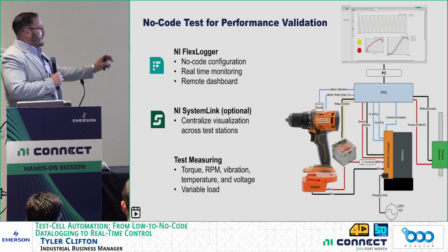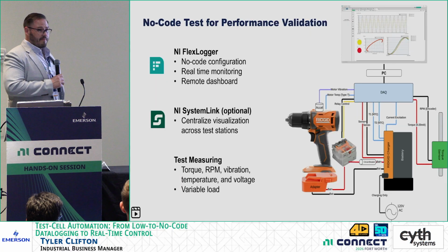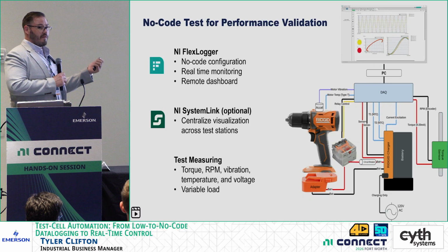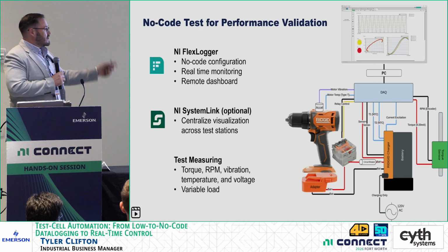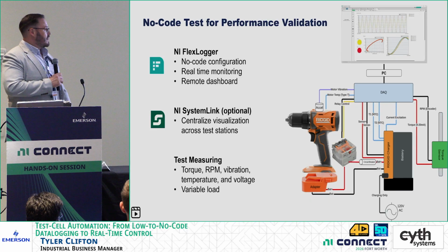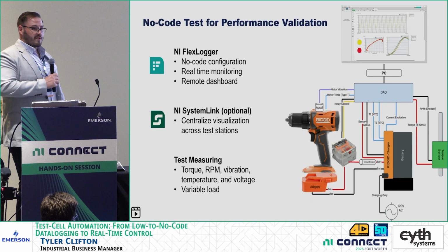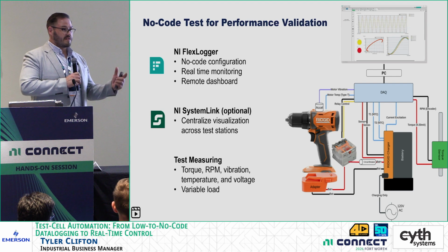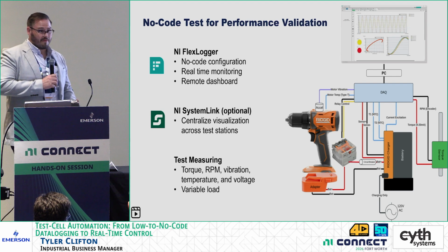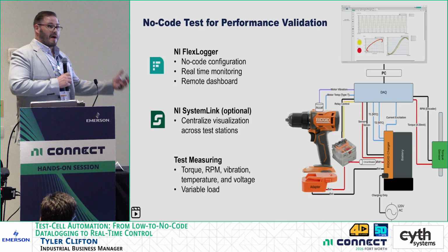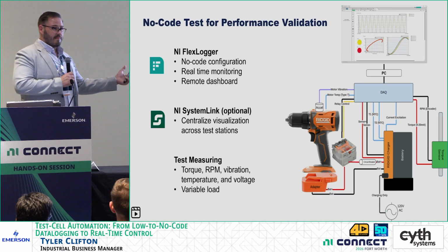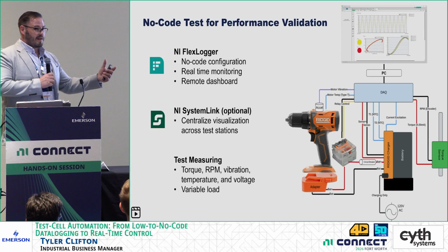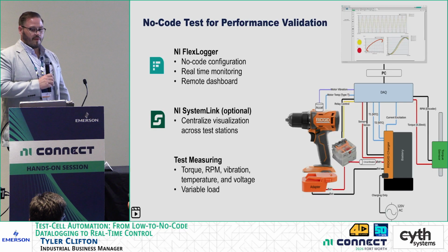Here we're showing you how we can make use of the NI platform, specifically using CompactDAQ and our no-code software called NI FlexLogger. This software is measuring torque, RPM, vibration, temperature, voltage, and applying variable load to our drill that's under test. So in this case, if you've had a chance to go down to the expo floor, there's a power tool demo there. This is actually that demo. All that's being done is the operator issuing the start to the test with the drill button, and FlexLogger is doing the rest.